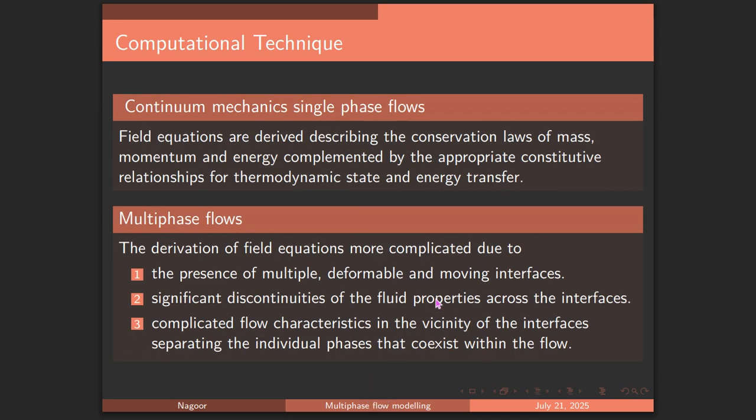So, coming to the single phase flows, as we use the concept of continuum mechanics and derive governing equations like the Navier-Stokes equations based on conservation laws of mass, momentum, and energy. Along with those governing equations, we also have some constitutive relationships based on thermodynamic state and energy transfer. And we close those Navier-Stokes equations with a stress-strain relationship with viscosity and heat diffusion coefficients.